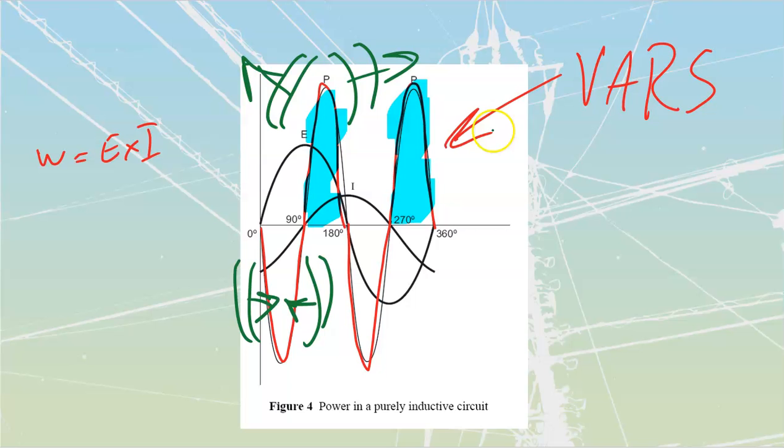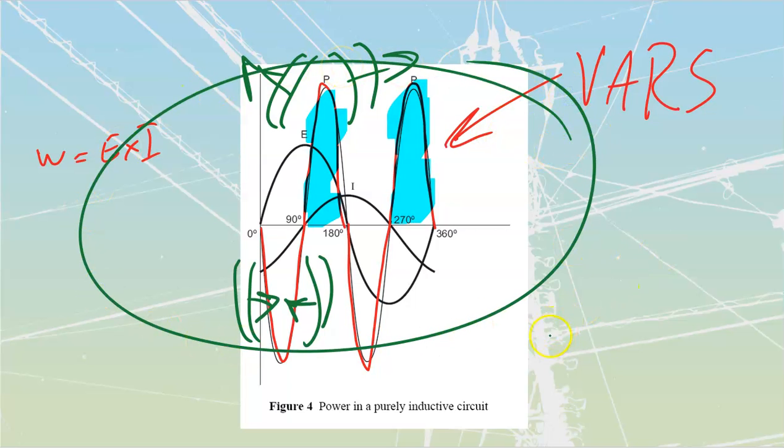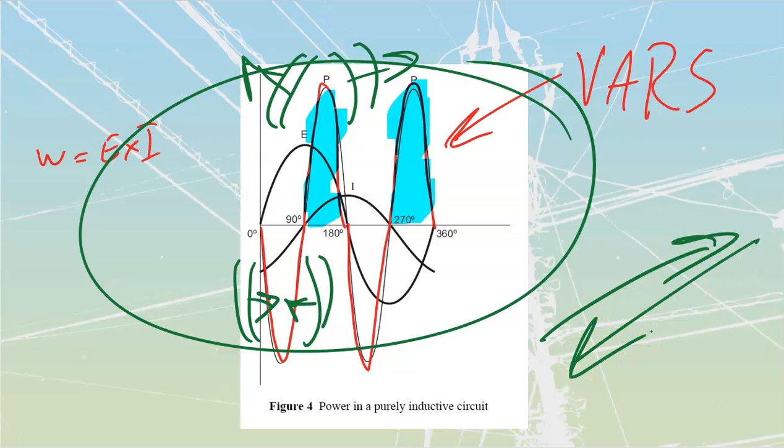Inside of a reactive type of circuit, we have current that we're going to remove from the supply, and then we're going to send it back in. We can actually send power back into a supply. It's 100% legit. It just gets diverted then out to other loads. So we're just taking current back and forth. As this current goes through our system, it does create other losses. And it takes up system capacity, because I have to use a certain percent of my system to deliver this current and send this current back that I'm going to have to reserve for it. We don't want to have a lot of this power. We call it reactive power, sometimes referred to as wattless power, and other times it is referred to as quadrature power.